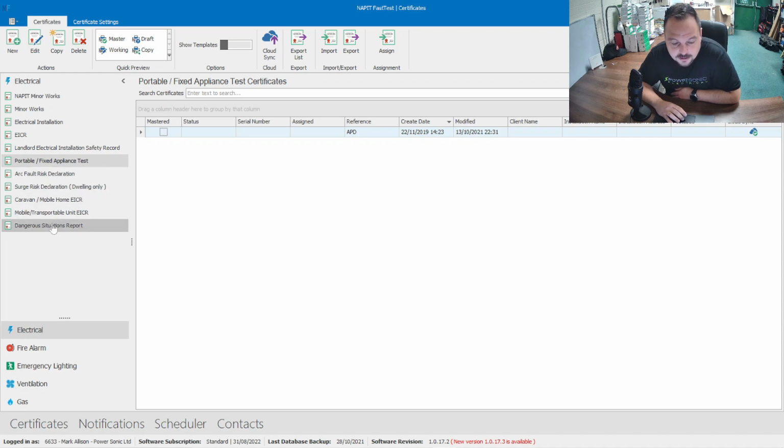And again, your dangerous situations report, that's a really good one for if you want to issue out a notice to a customer that you can record to say you've observed something that they need to take action against. Really good one. The one I like the most though is this landlord electrical installation safety record, and this is a way you can tie your